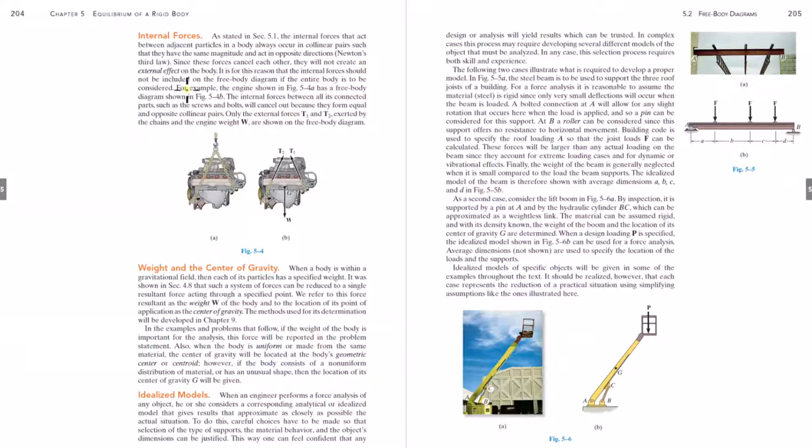All right, internal forces. I go into detail on internal forces in the full-length free body diagram video. Again, the link is posted in the description. We don't consider internal forces in free body diagrams, only forces on exposed surfaces. For all the exposed surfaces in the free body diagram, if there's contact at those exposed surfaces with something from the environment that we took that body from, then that's where forces are going to be. And then there's also non-contact forces, weight.